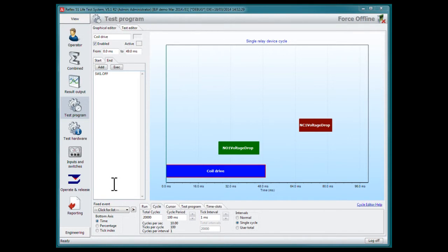However, when testing a large number of cycles, for example some tens of thousands or even millions of cycles, the data reporting is more sensibly performed every few hundred or few thousand cycles, because trends are still clearly visible on a graph over life test of some thousands of points, instead of having to work with data where there are literally millions of points to plot.